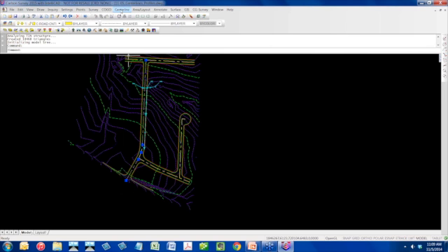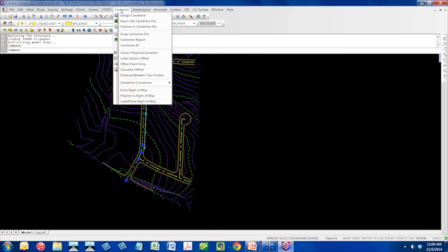So what we're going to do, we've got this polyline in the drawing. It's got our centerline curve and everything already built into it. Again, I'm under Survey, so you're going to find it under the Centerline menu. In Civil, Takeoff, Construction, you'll find this command in those as well. And I'm going to use the Polyline to Centerline File command.